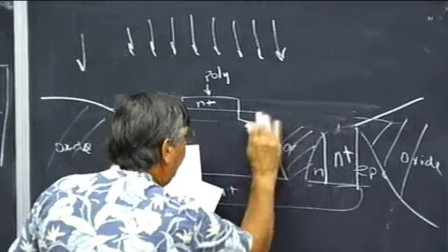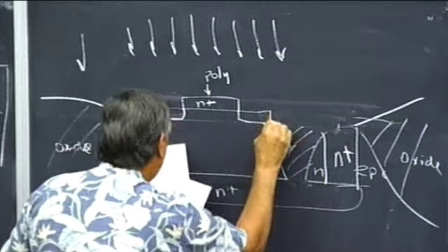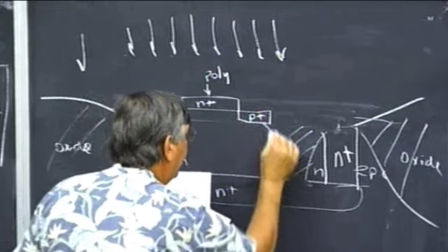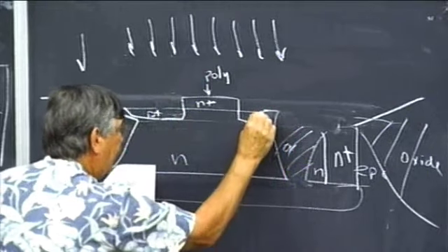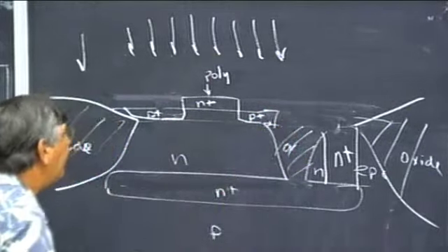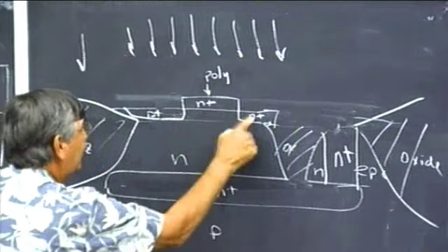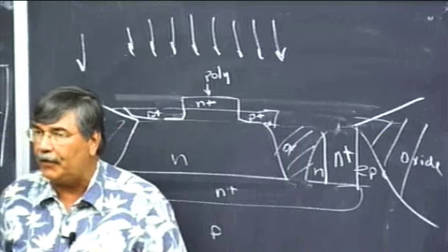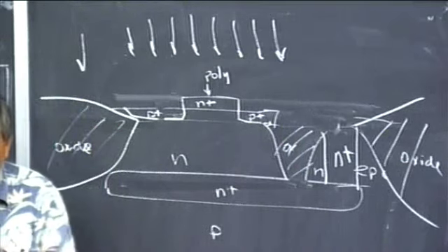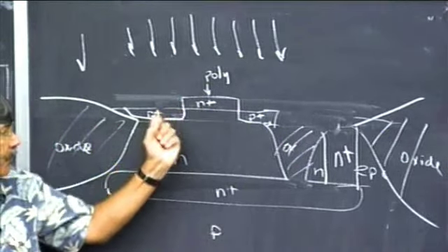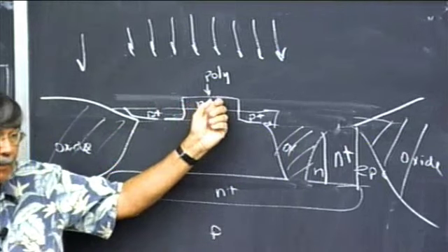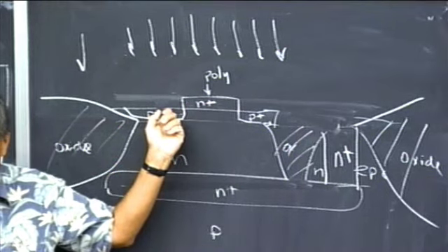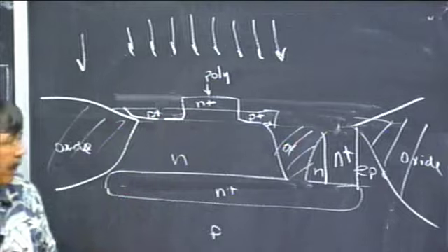And if I did this right, I guess this is going to go, I think I put this too far. It should have been patterned to be over here. So this is going to be p-type over here. Doesn't really matter over here. This will be fine. All right, so I think that's right. But the main thing is that it's self-aligned right here. So in many of the processes, as you see MOSFET stuff, you don't have to worry about two masks. This thing determines, the location of the N plus determines where the P plus base, heavily doped base part is.